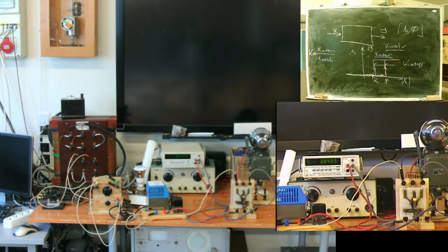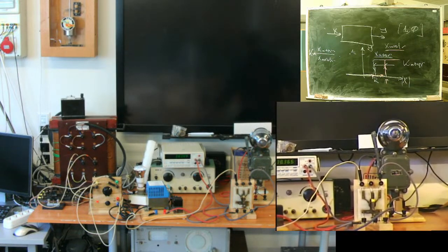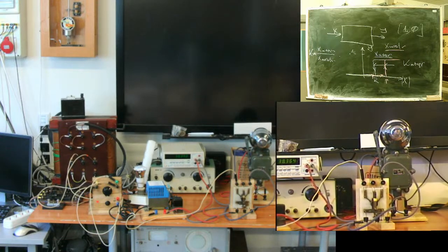For modern digital relay, this difference is programmable and about 4-5%. For old mechanical relays, a current relay is usable if this value is 0.83. Not less than 0.83.